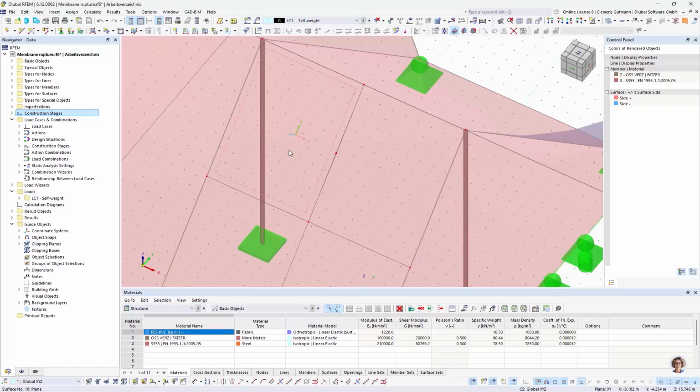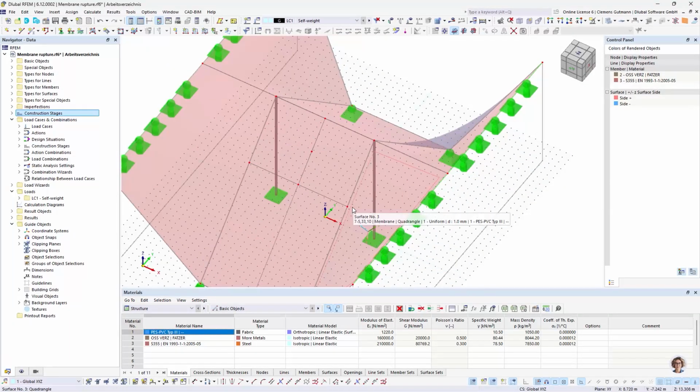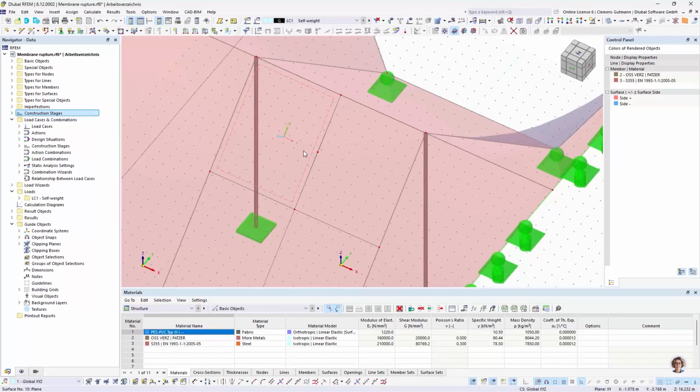And what we don't see is how the panels are actually placed on this membrane. For this project, I imagine that there is a weld here at this line and also at this line, and the weld has roughly double the thickness of the membrane, and therefore is a lot stiffer, and it's not very likely that the weld itself will rip.